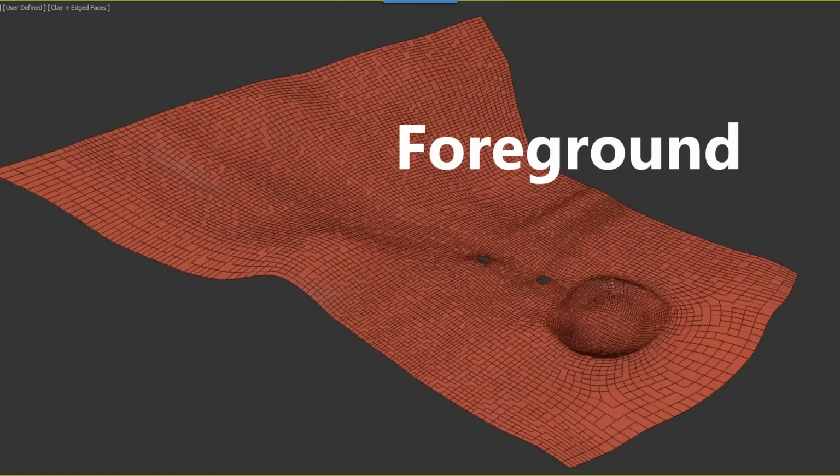Sometimes if you're using geometry that's come in from more of a displacement style of terrain creation, what you'll find is you get small spikes, very irregular, uneven geometry from one poly to the next, which can cause problems when scattering large areas of grass, for example, using patches, because these patches will end up on end or something like that, and they won't look like the final render. So simple foreground modeling is often best done like this.